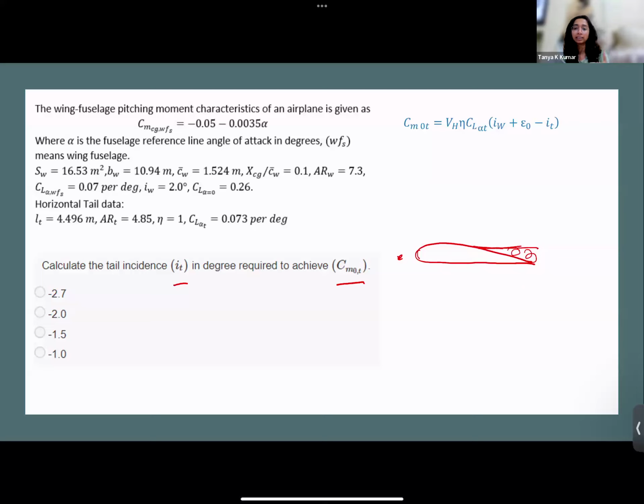One of the cases where this happens is where there's a sudden increase or decrease in angle of attack. So when the aircraft is flying at equilibrium or at some condition, there's a sudden increase in angle of attack, either due to pitch up or due to a gust. The boundary layer at the leading edge separates, and due to this, vortices are formed at the leading edge.